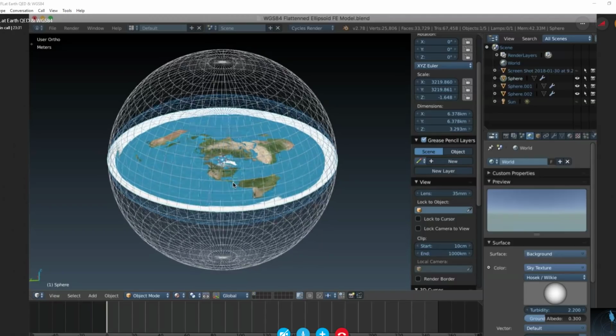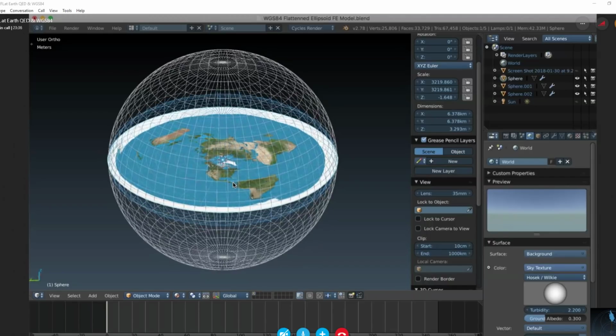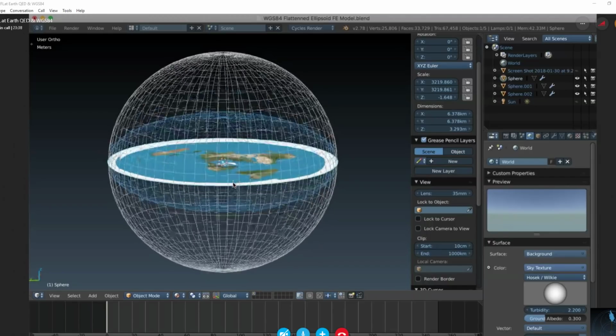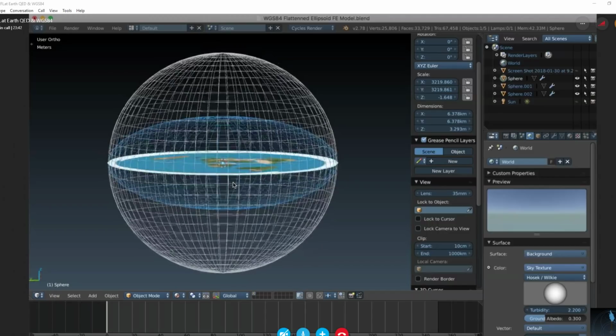Sure, but as a surveyor, as far as you're aware, you're on a globe. So you're on, let's say you're in Central America or North America. Keep it easy. You're on that point in your mind on a sphere. So you'd find that point on the geoid Earth, correct? Yeah. And that would be basically you would have to survey it relative to your datum point, survey it to the stars, bring it down to the geoid, and then flatten it.